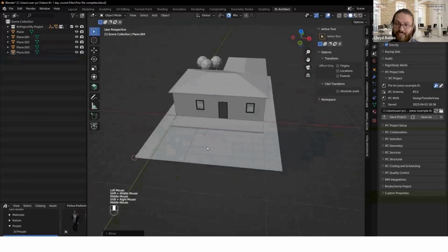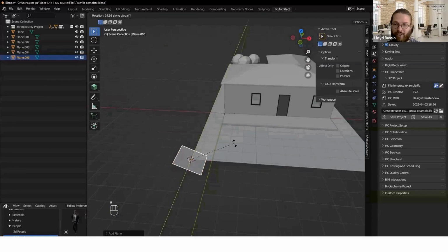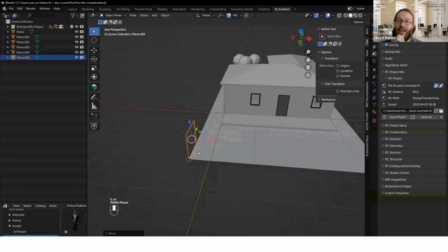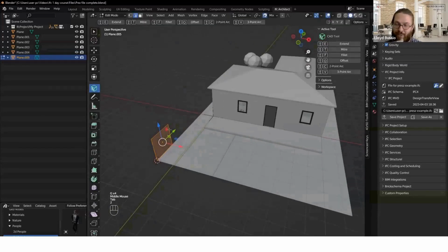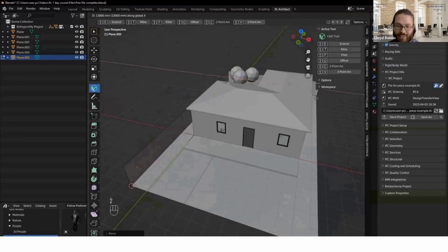So we're just using the model we created with BlenderBIM, which is an IFC model. And now that we're using Blender natively, this is no longer an IFC model. It's just a blend file, which is Blender's native file format. So here I'm just creating the boundary wall. I'm using a plane to extrude it, and I'm just snapping it to the edges and constraining it. It's very quick.